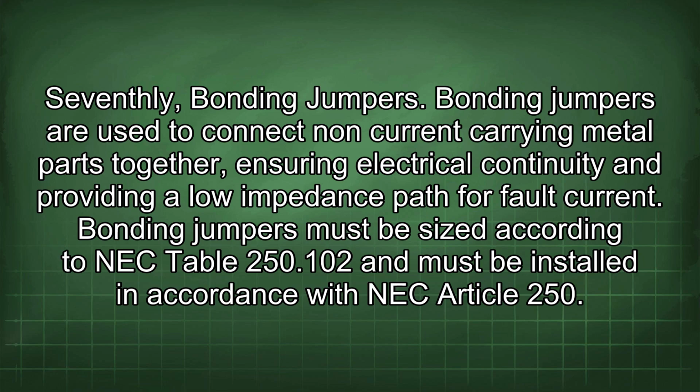Seventhly, bonding jumpers. Bonding jumpers are used to connect non-current carrying metal parts together, ensuring electrical continuity and providing a low impedance path for fault current. Bonding jumpers must be sized according to NEC Table 250.102 and must be installed in accordance with NEC Article 250.